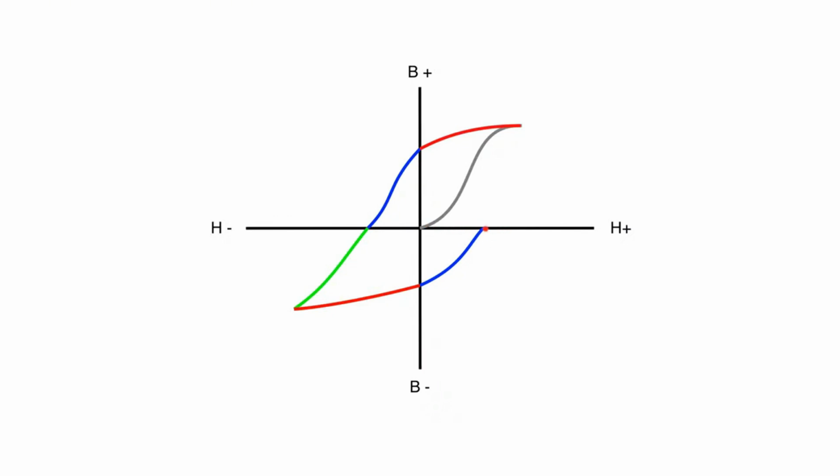And again, if we left the magnetizing force on in that direction, it would continue to go. So again, we had to coerce it. So this is our coercive force at this point here, which we can see with the big C. So again, if we were not paying attention and we left our magnetizing force on, it's going to go in this direction again and still hit saturation. We can see that it goes back and hits that point of saturation again, and the whole thing continues again. So what we end up with is what's called the hysteresis loop.